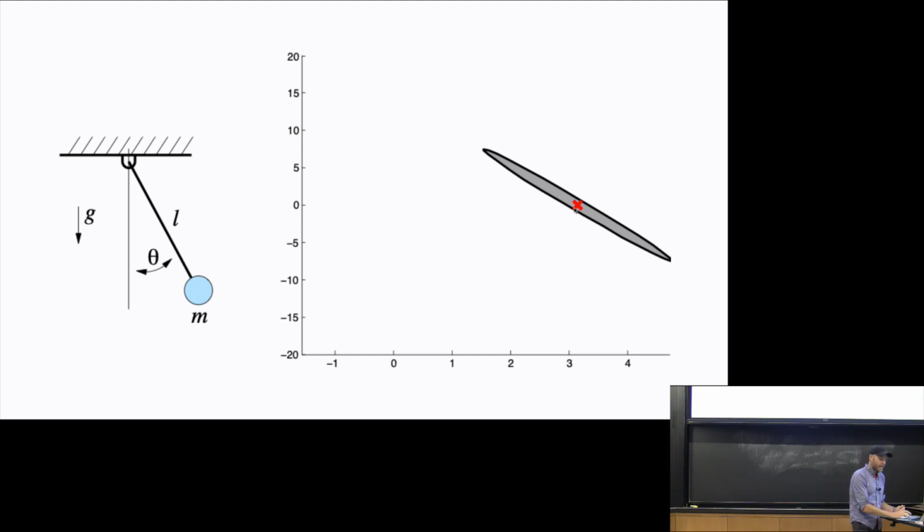So like in RRT, we'll pick a random point in the state space. This time, if it's already inside a region of attraction, if it's already inside the gray region, we can just reject it. So like the RRT, by rejection sampling, our sampling distribution is changing over time, but it is uniform in the currently not stabilized regions.